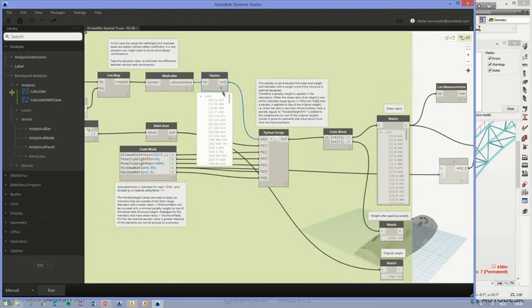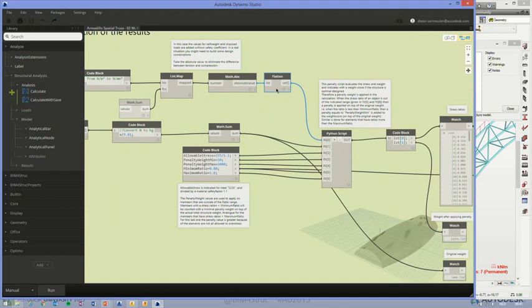It's exactly the same, except for the end, where the results that will be read will be different. I only want the maximum stresses in the whole structure, and the total reaction forces from the points for the case self-weight. If I have those reaction forces, this means I have the self-weight of the structure.